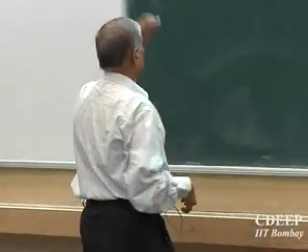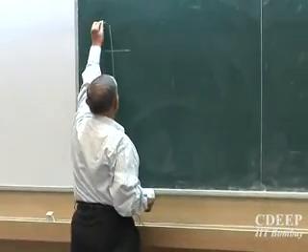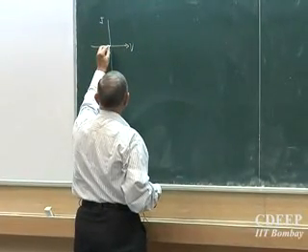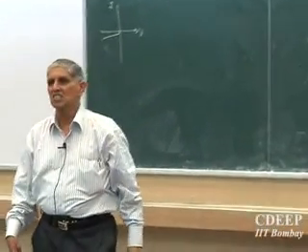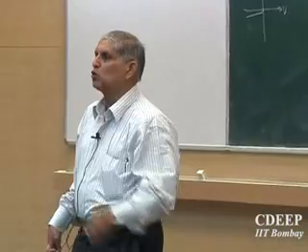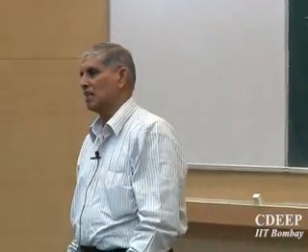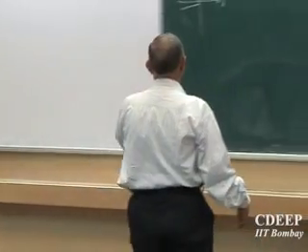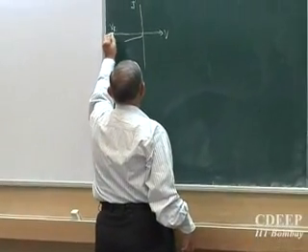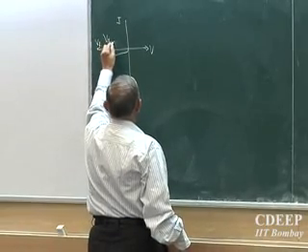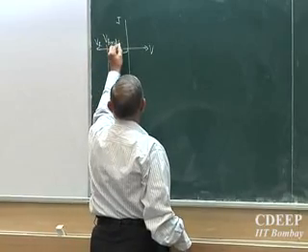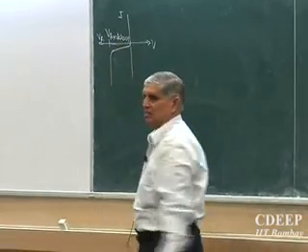So we start with the last part of PN junction. For the diode we have seen that the current-voltage characteristics under reverse bias show two components, one which is constant with reverse bias, the other which varies with reverse bias, which we call the generation current. However, if we keep increasing the reverse bias, somewhere around one value which we call breakdown, VBR, the current starts shooting up again.